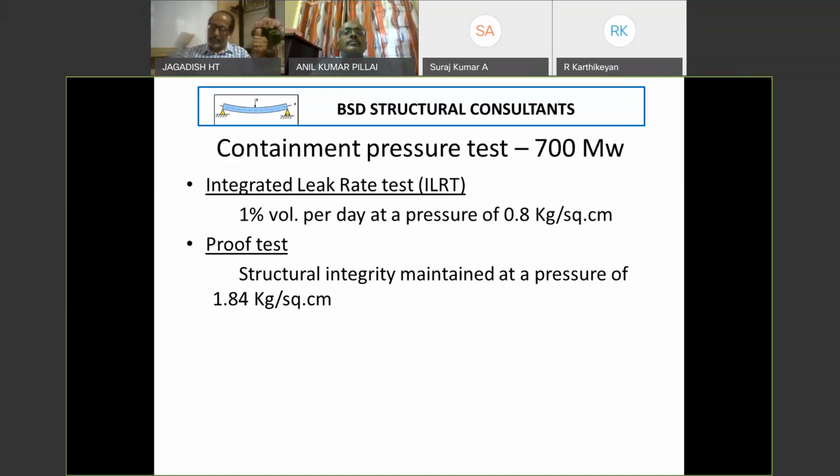So we pressurize water, increase the pressure of water, so the temperature drawn from the reactor may go up to even 250 degrees centigrade. So high pressure water is passing through this cooling system. If it starts leaking out, it increases the pressure in the containment, because containment is also a contained volume of air. Anything increasing pressure in a volume of air starts increasing temperature, increasing pressure in the containment. So the inner containment starts getting pressurized.